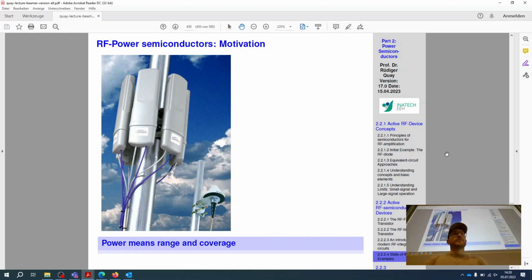Nowadays, what is being done with 5G is that multiple transmitters are integrated into one transmit station, and these are used to target more refined chunks of a transmit area, and in these more refined chunks to transmit a controlled range of power.